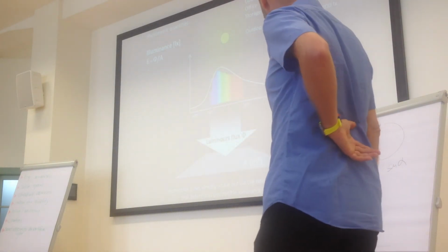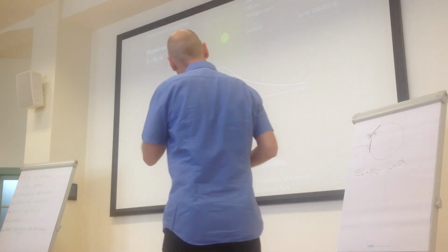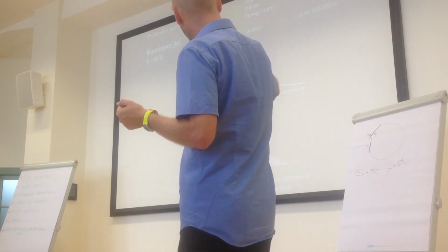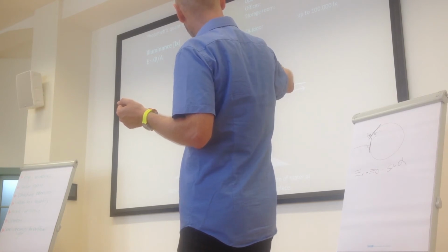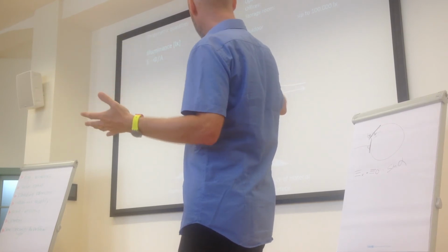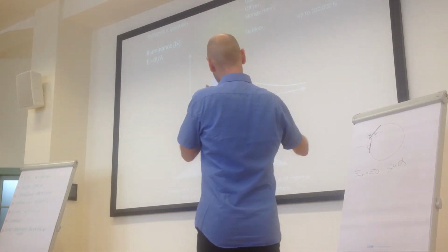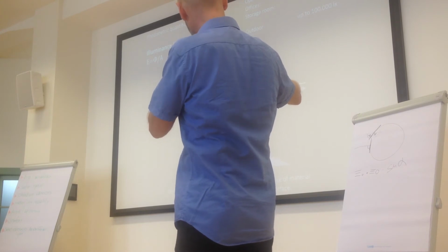I have picked out some typical amounts of lux. For instance, in an operation room in a hospital, there is a requirement of about 10,000 lux. In office buildings or in universities or in seminar rooms, there is a recommendation of 500 lux.